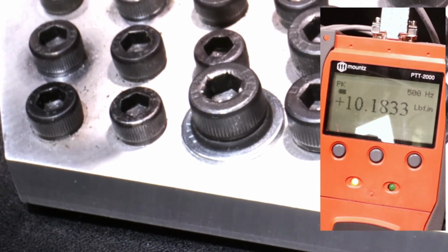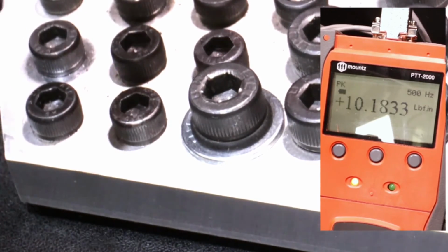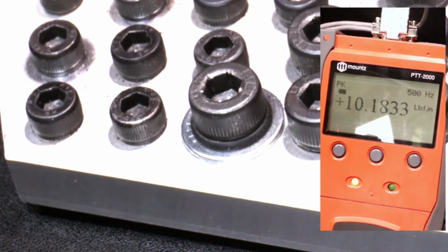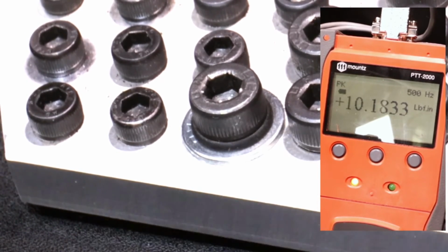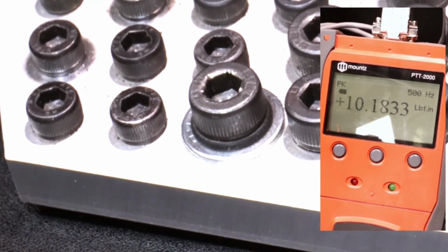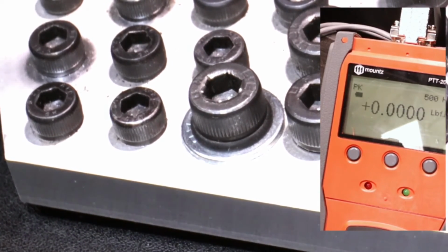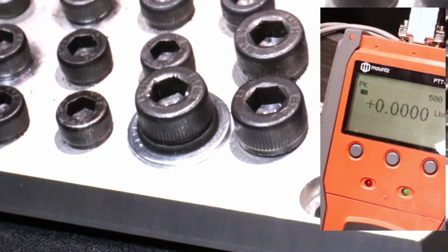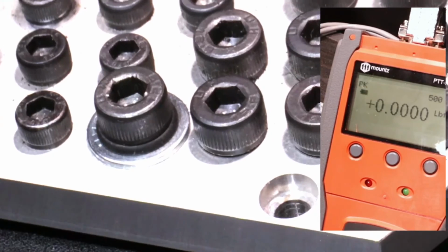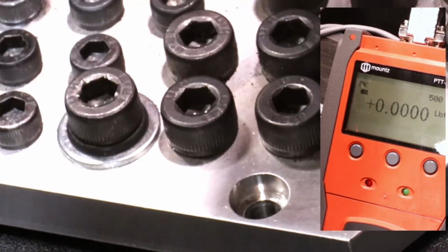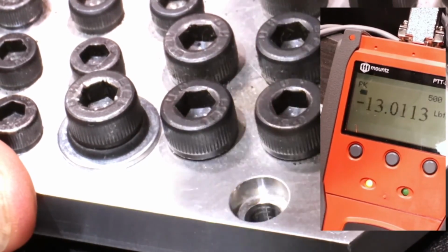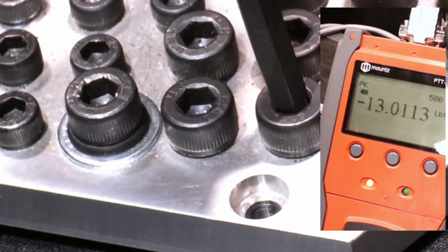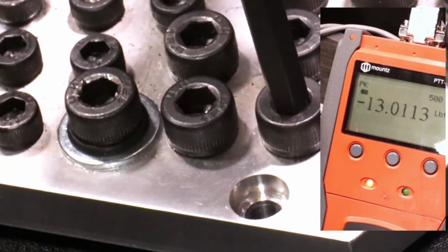Next, if we want to go ahead and do a breakaway torque, we can sample that with these three fasteners, and that would put us at what would be a negative number on the display, because we're actually running it in the opposite direction. And so as we do that, I'll turn it until we get it loose, and you can see we're at 13, and we may see the torque increase based off of the different fasteners that I have here. Yep, 16.